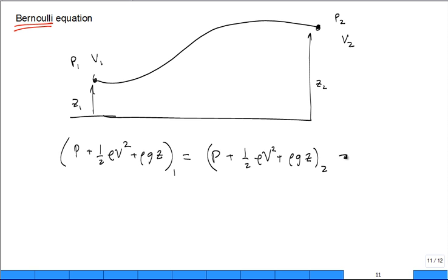It's always a constant along the streamline. There are a couple of assumptions in there. The fluid isn't being heated up so it expands. There's no viscous dissipation of mechanical energy. But P plus 1/2 rho v squared plus rho gz is equal to a constant. We apply that from inlet to outlet along a streamline in a lot of applications.